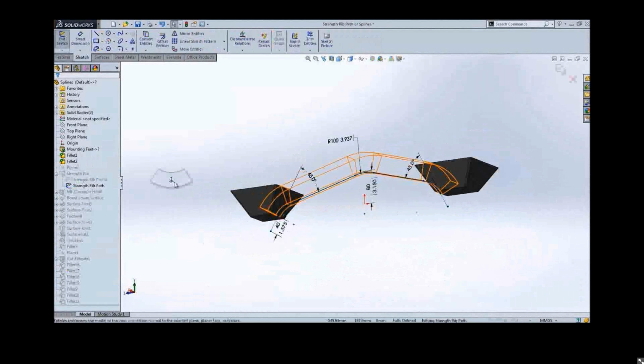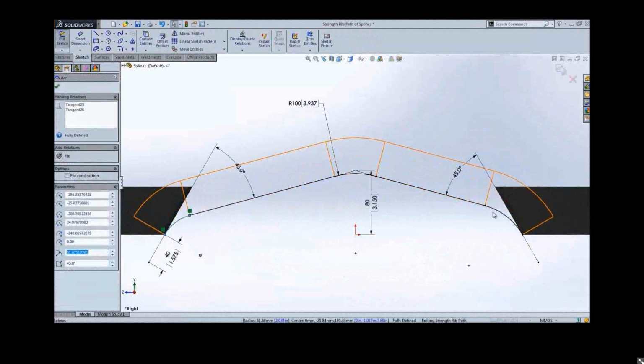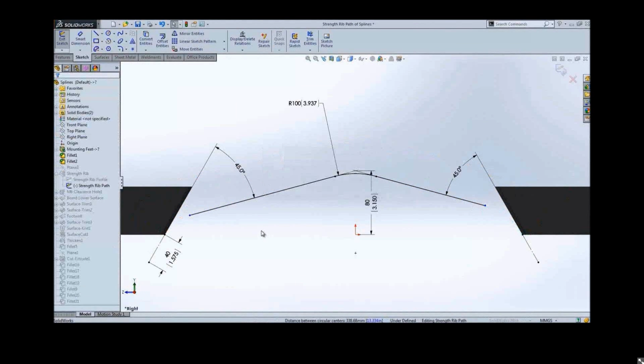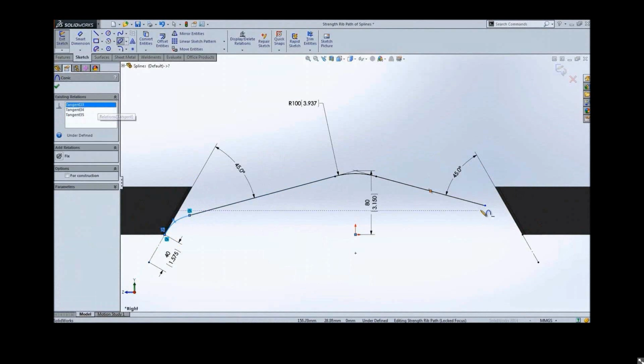The path of the sweep used in this is currently just a line and a couple arcs on the end. These are just normal arcs. So what we want to do is replace these with the new conic fillets. We can just delete the arcs and put a new conic in there. What you're going to notice is that the conic automatically goes tangent when you put it in. This is a really nice, time-saving feature that they just automatically put in.